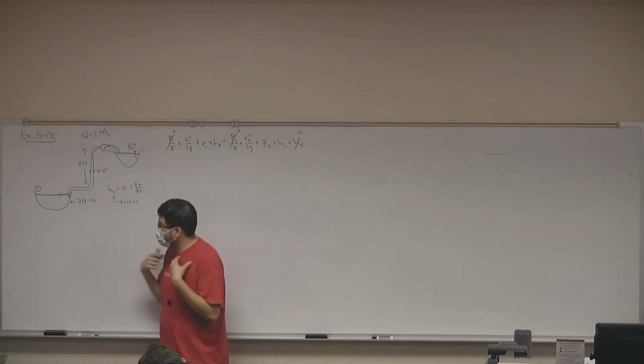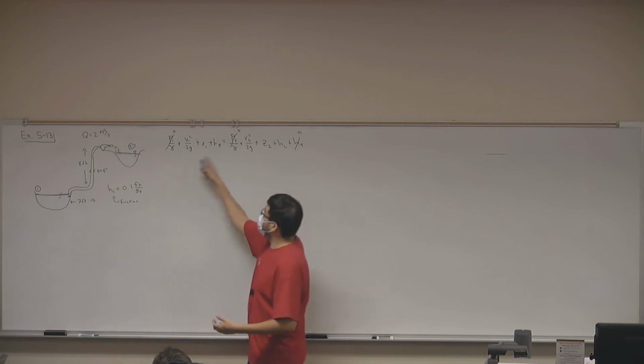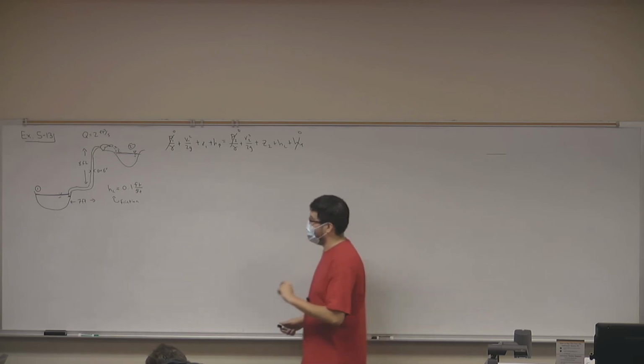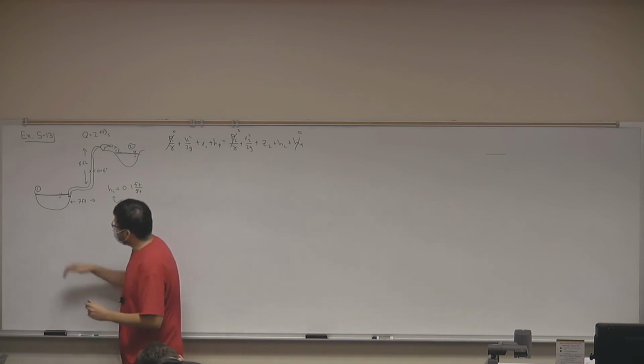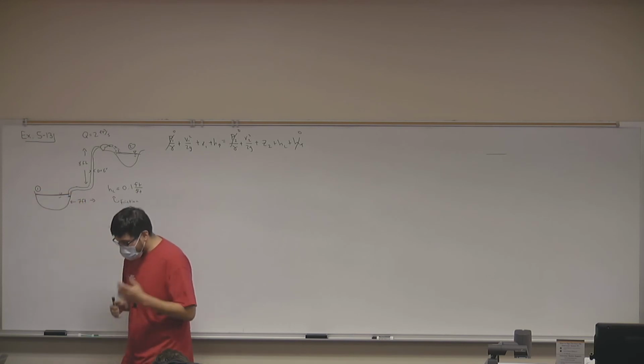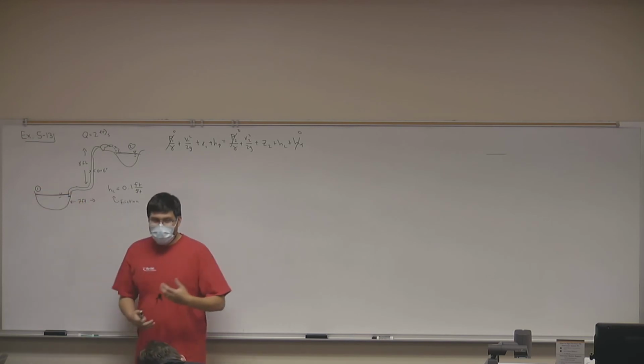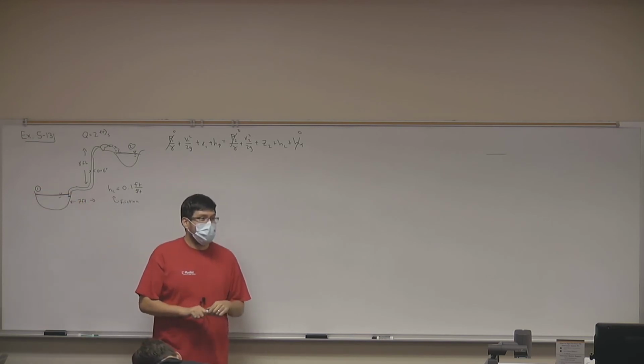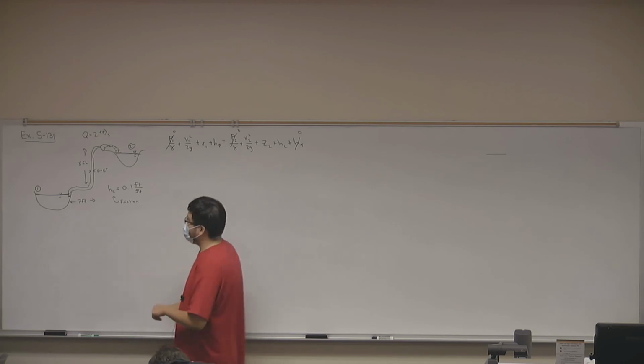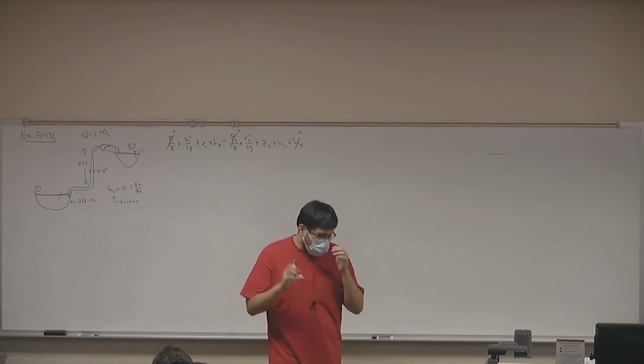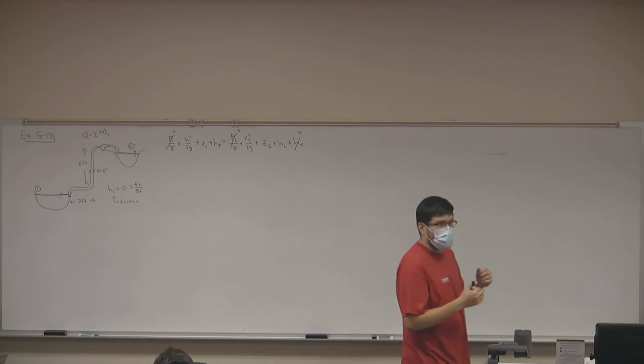And if it were me, I would always select my surface because I can always cancel out my pressure. Now think of velocity, and this is interesting. What's the velocity of this control surface? 0. Why? It's standing water. Technically, if we want to be as precise as can be, it is moving, but at what rate?